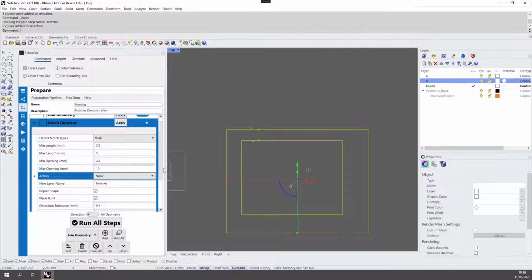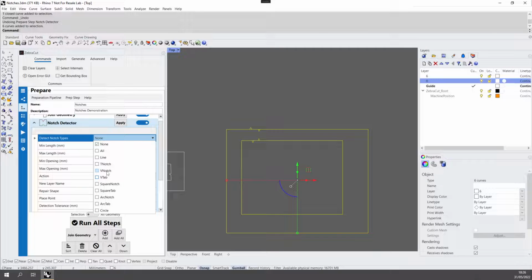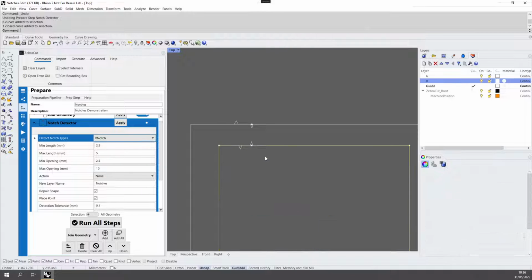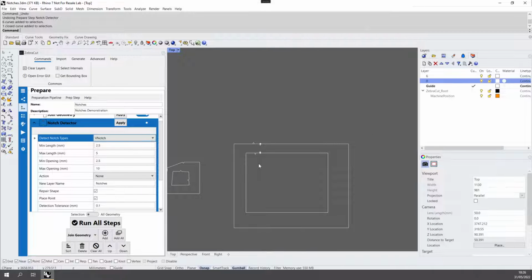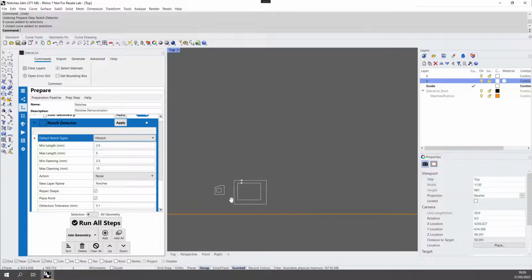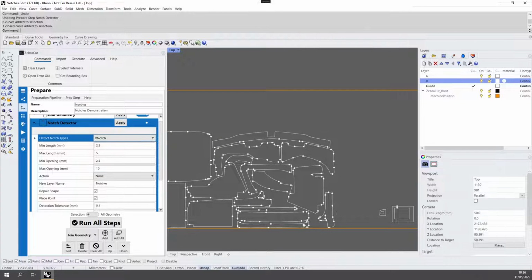Correspondingly, I can also then do that on just V notches as well. So in this case, if I run that, you'll see I just get the two notches. But again, if you were to consider this shape individually, you might think that is actually a tab. But ZebraCut is intelligent to do with your nesting, and you can nest through multiple layers as deep as you want, and ZebraCut will allow you to flip between notch detection and tab detection appropriately based on what you specified. So we can do notch detection within nested parts as much as required. Okay, so that is notch detection.